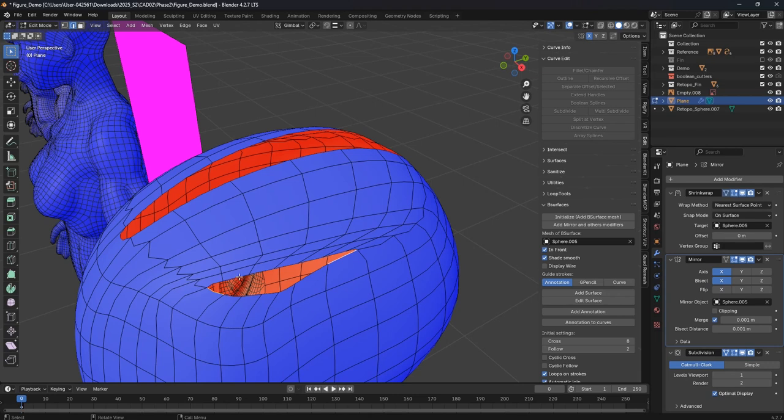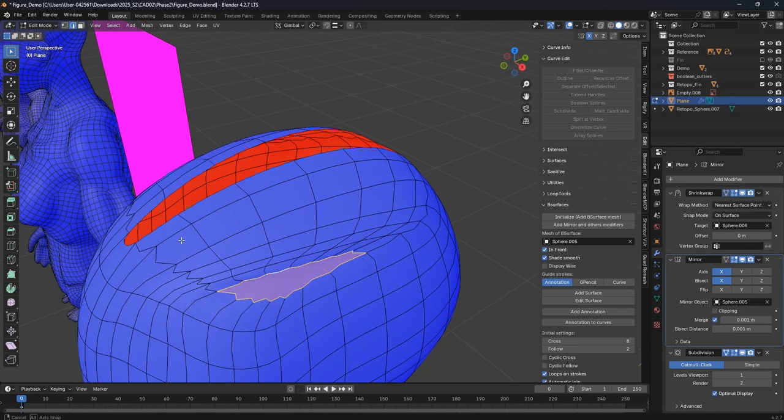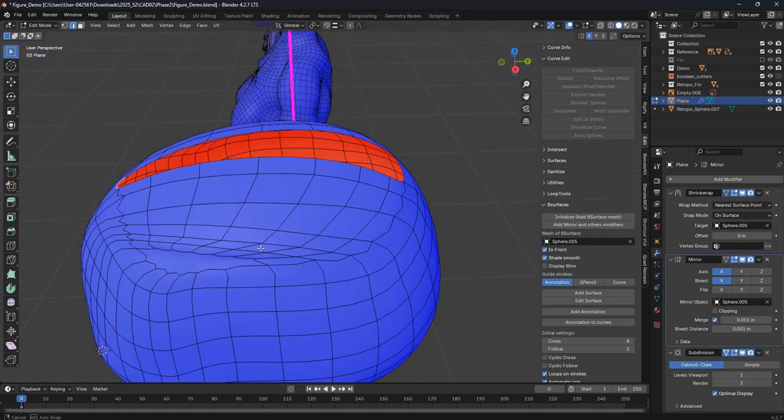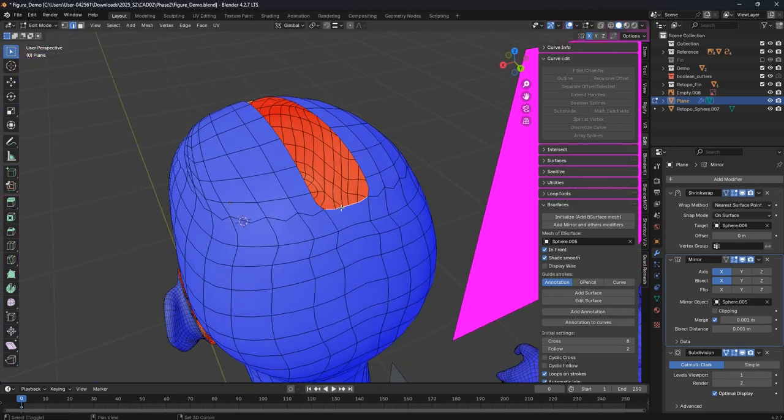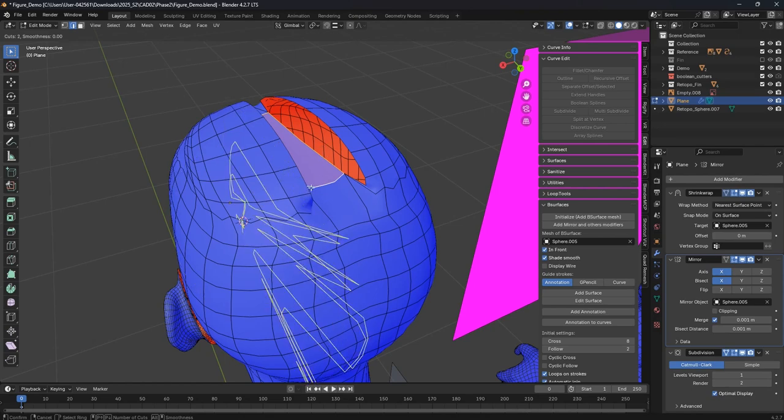So actually, I would say let's try to hold on your Shift and Alt key. Select all the edges, press the F key, and then we can try to connect them together. So that will be the last part. For the middle, let's do the same thing. Press the F key, connect them together. Ctrl and R, using loop cut to increase the number of segments in the middle.